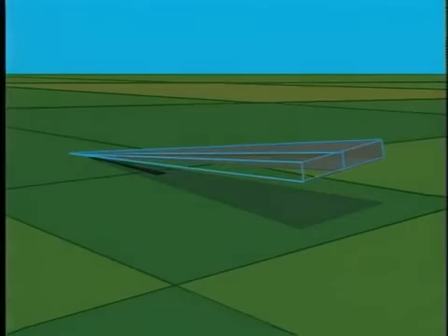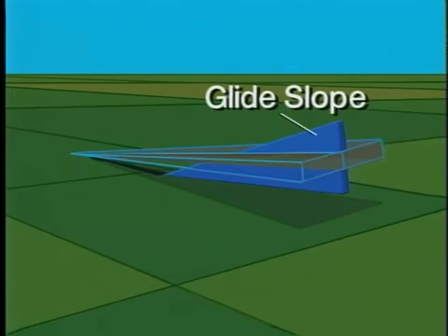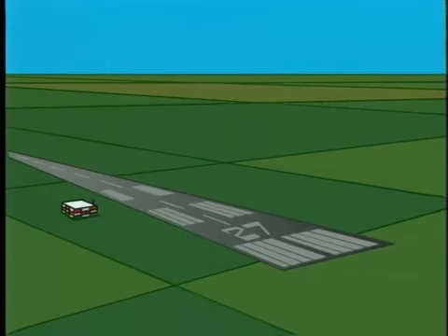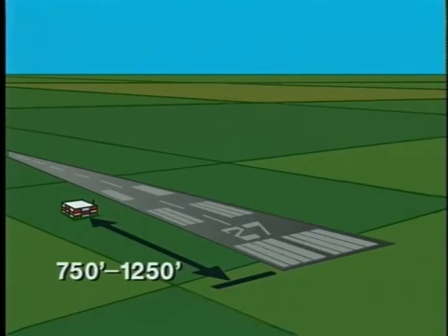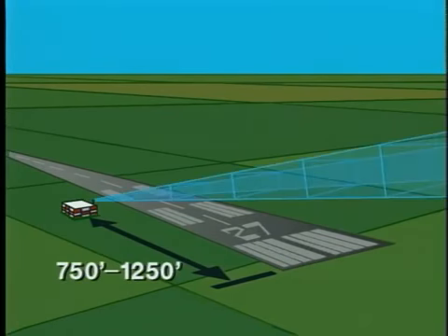During an ILS approach, vertical guidance is provided by the glide slope. This signal allows you to navigate along a glide path to the runway. The glide slope transmitter and antenna are usually located to the side of the instrument runway center line and 750 to 1,250 feet down the runway from the approach threshold. Normally, this signal is only directed to the front course, and since it is offset from the runway, it may not provide guidance all the way to touchdown.